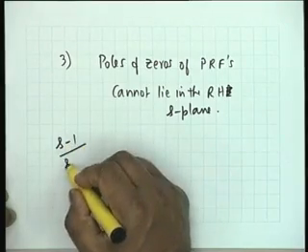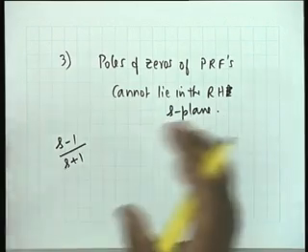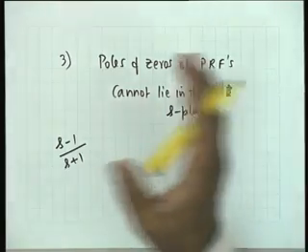No, that is not correct. Because for a transfer function, which is not necessarily a PR, there can be zeros in the right half plane. For example, I can have a function (s minus 1) by (s plus 1), which is an all pass function, as you know. The poles and zeros are in mirror image symmetry.